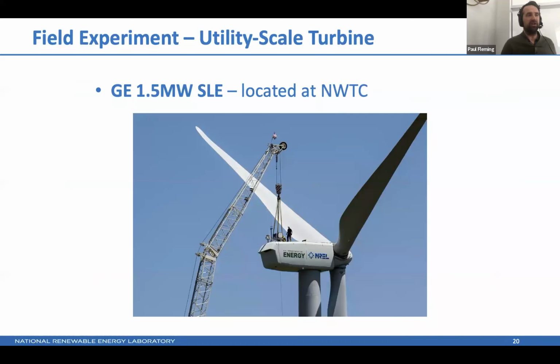So as you go down the rows, you see the green circle is showing the FLORIS is expecting the wake to be inside this green circle. As the turbine yaws more and more, the wake should shift. And as you go downstream from left to right, the wake should continue to move over a bit. And that is not too far from what we observed looking at those LiDAR scans. So this was an early result, in the physical world, looking at wake steering.